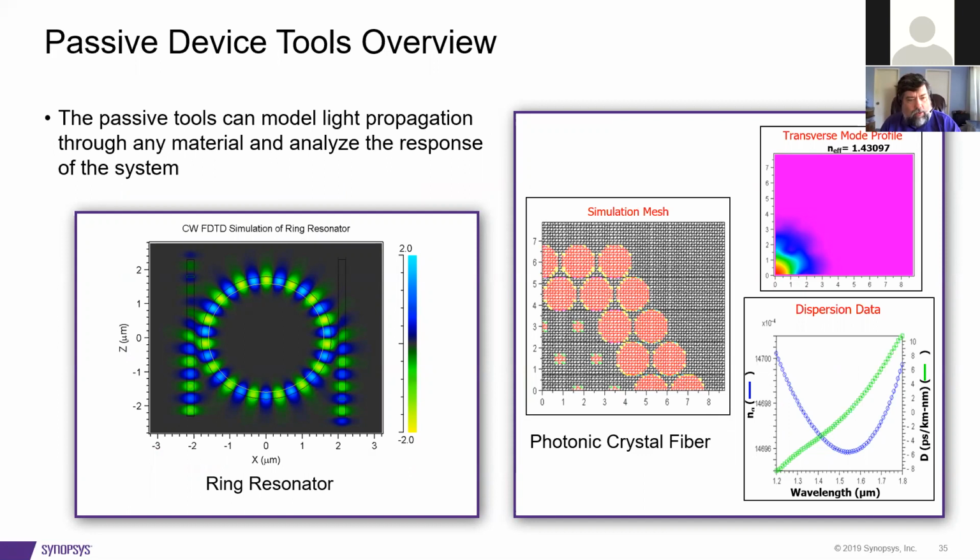But this is a ring resonator. This is used as a kind of an add drop, selective for particular wavelengths. On the left-hand side, you'll see we have a fiber. These green and blue light and dark pieces are actually the representation of the electric field, so both positive and negative, the wave as it goes up and down. And here we have a ring. These do not touch, but the wave couples through the evanescent wave, and it couples in here.